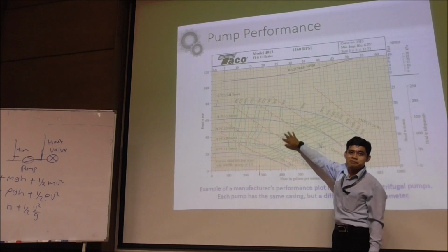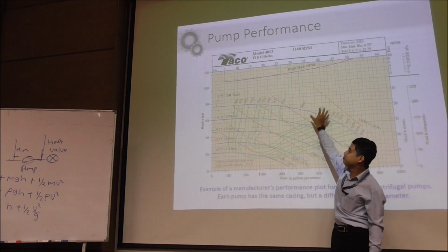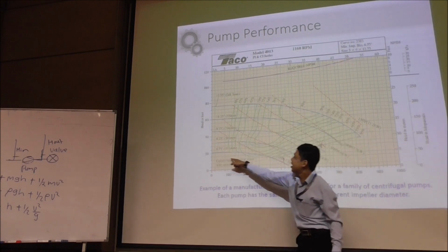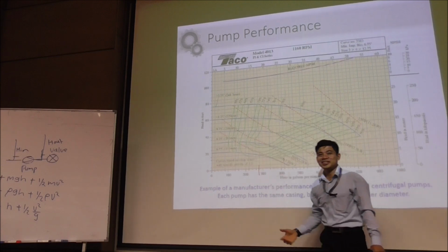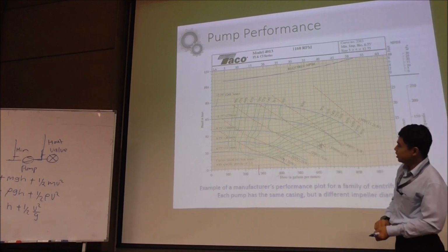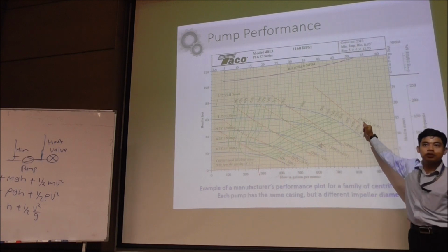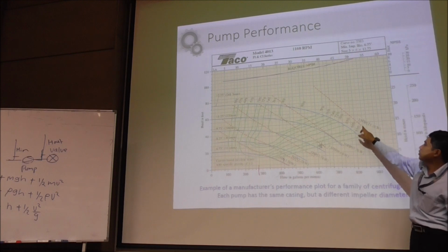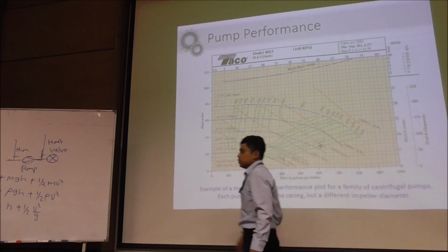Topography map. Right? I would love to put this one in your variable. Right? And you can draw the system curve here, find the best pump and so on. Yeah? It happened last time. May happen again. Okay, so that's what you have. And this is the power. This is the peak power. This is the maximum power that will be drawn by the pump. So you can see here, 15 horsepower, 7.55. Right?